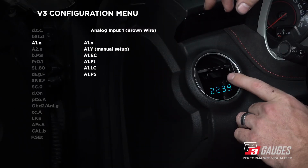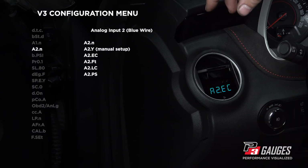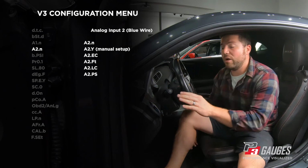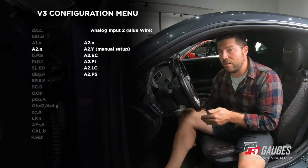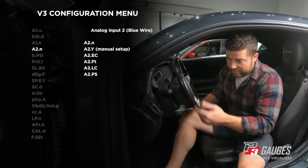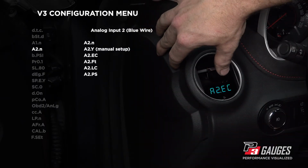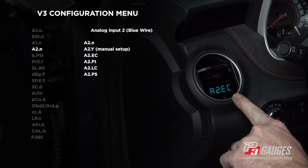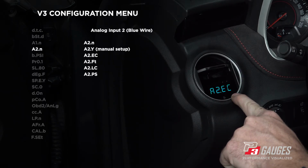So once we have those set, we go to the right button one more time. And now we're at the A2 setting. So A1 is completely set up at this point. Now we're on A2, which is your second analog input. And this is a good time to go over, we have some pre-configured settings on here. As you'll notice, this says A2.EC, which means it's pre-configured for our ethanol content.